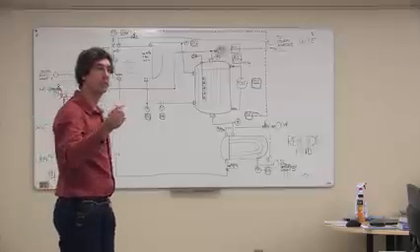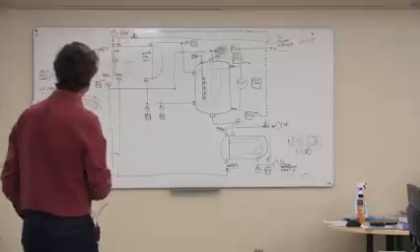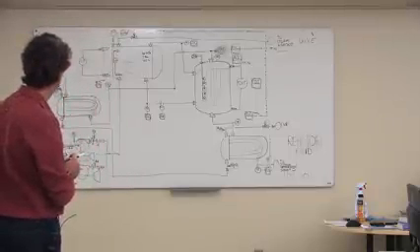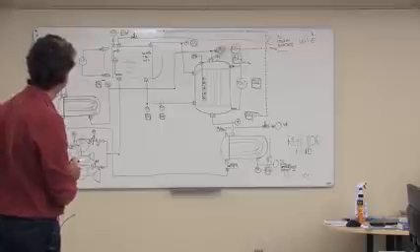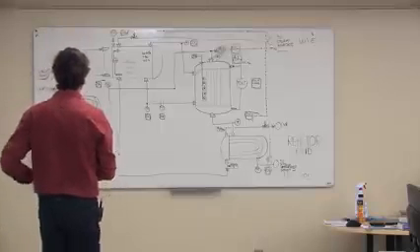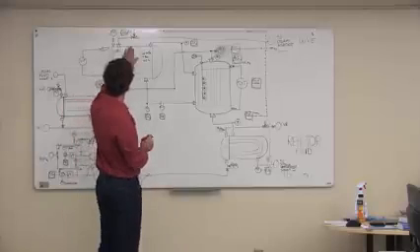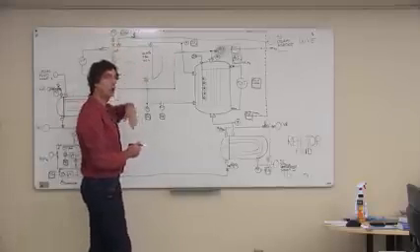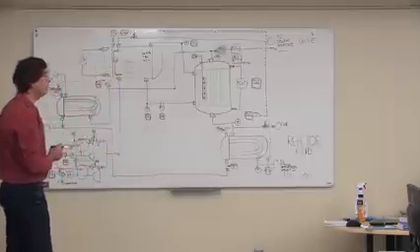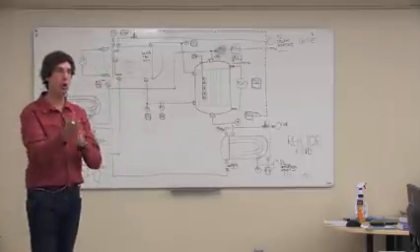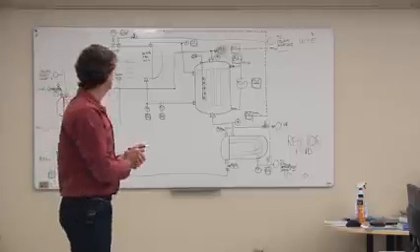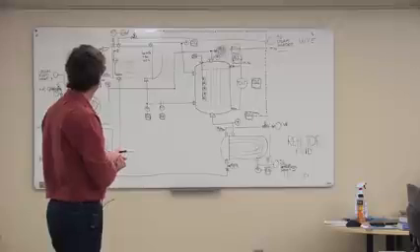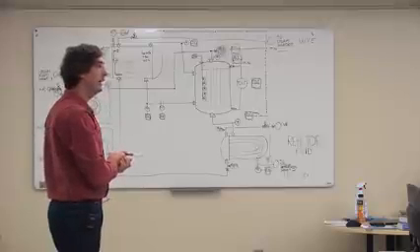We connect the relief valve to the level transmitter. You mean the pressure control valve? No, because we've already got the pressure control valve tied up in an existing control loop. We'd end up with two controllers trying to get inputs from two different measured variables. That wouldn't really work. Any other thoughts?